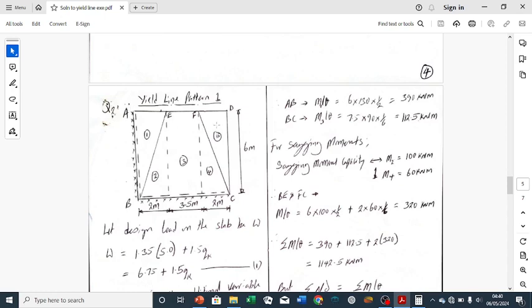Then m is the moment capacity across the span AB, which we have said is 130. And theta: this is the place where we are doing this rotation, the point of maximum displacement, and the distance is 2 meters. So theta is 1 over 2. So having done that, we calculate our hogging moment AB.